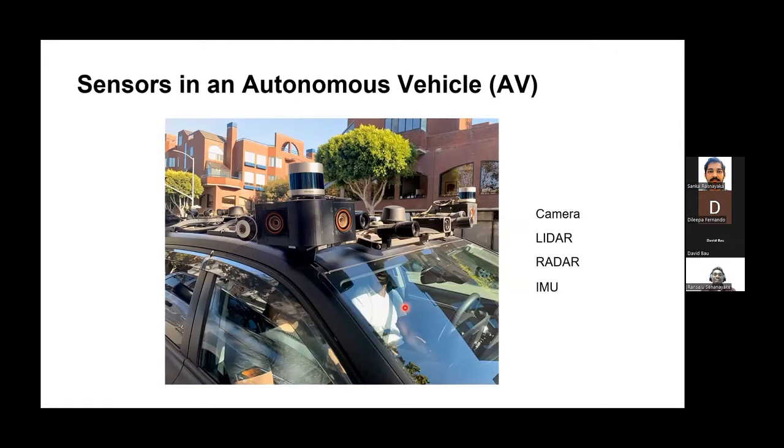The running theme for today is autonomous vehicles. I will quickly explain what kind of sensors they have. They have cameras, you can see here, just regular cameras. They have LiDAR, which are basically depth sensors. You can measure the distance to nearby objects. They have radar, so you can get the velocity. Some of them also have typical time series data, such as what you get from IMUs. I want to focus on LiDAR.